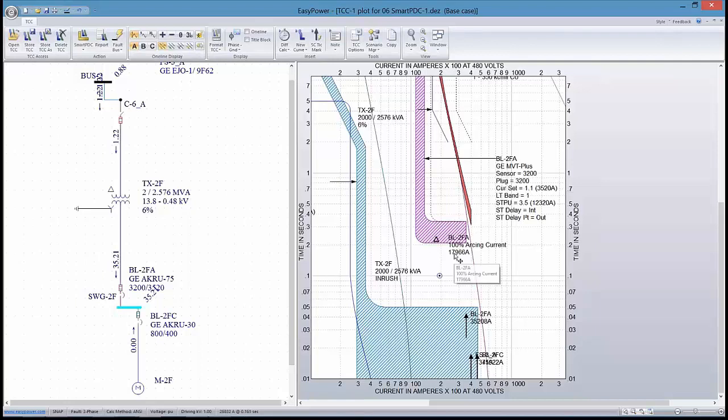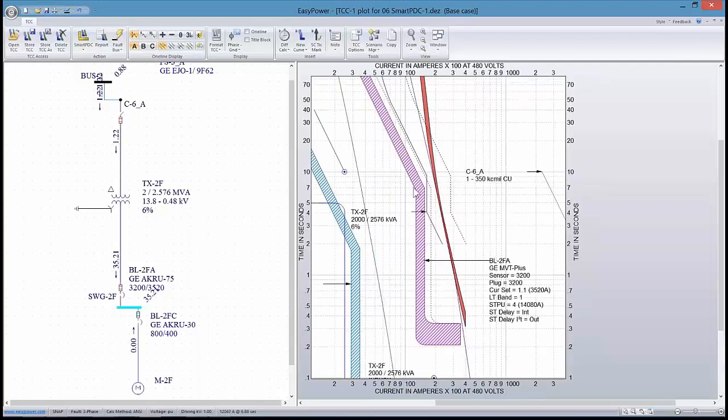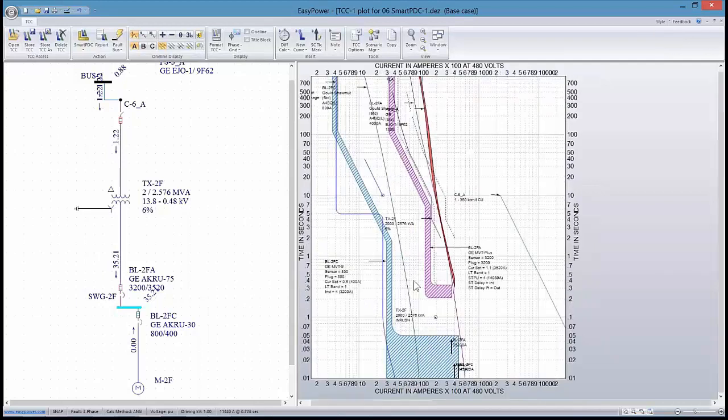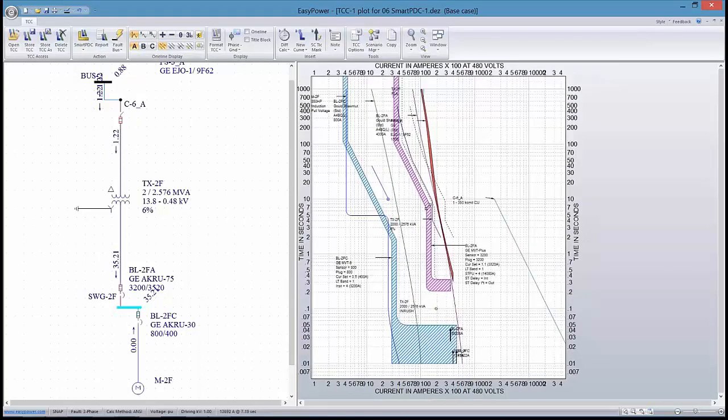And so that's going to be somewhere down in this area. As soon as that 85% mark, if I adjust the curve to the right, the 85% mark falls now into this vertical section, my worst case trip point now becomes a much higher value.